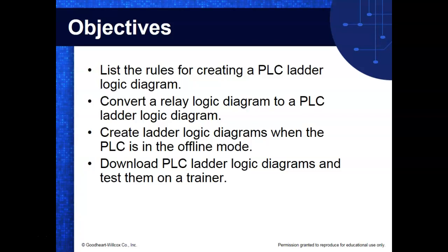Anytime we create a program or modify a program, we have to bring the application into offline mode. Some of your newer PLCs allow you to update and modify online. It's really neat: you set up a dummy rung, and it keeps the original rung. So if the rung you inserted doesn't work, you can always go back to the original. A lot of your newer PLCs support online editing, but with RSLogix 500, you have to bring the application offline.